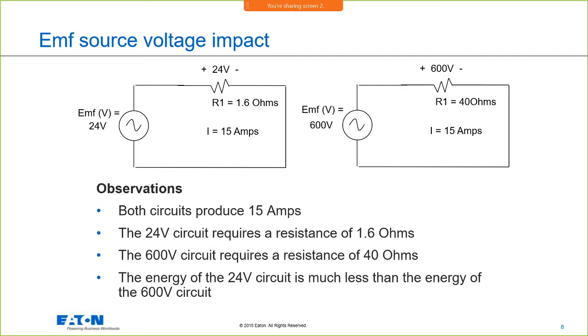We'll test them at lower voltages, get the same amps, because the amps is what makes a circuit breaker trip. So I can establish my trip curves based upon the amps and keep a low voltage, but just drive that amps. And this is important because the trip curve does not change based upon the voltage. If you're just looking at a TCC curve, you can say, well, this is a time current characteristic curve at what voltage? Well, it's whatever voltage that you apply. It's depending upon how much current you are pushing through the system.